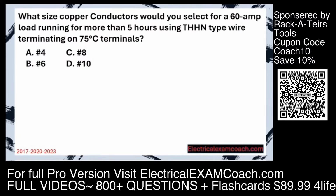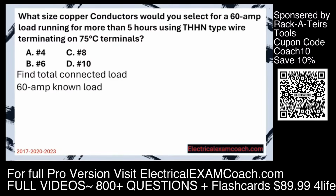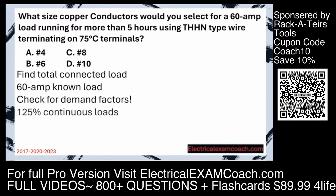What size copper conductor would you select for a 60 amp load running for more than 5 hours using THHN type wire terminating on 75°C terminals? Step 1, find the total connected load. Well, our starting known load is going to be 60 amps, but we must check for demand factors. When we find out that it's going to be a continuous load, we need to remember to do our 125% rule for continuous loads. So we take our original known load, multiply it by 1.25, and that gives us a new known load of 75 amps to size our wire by.